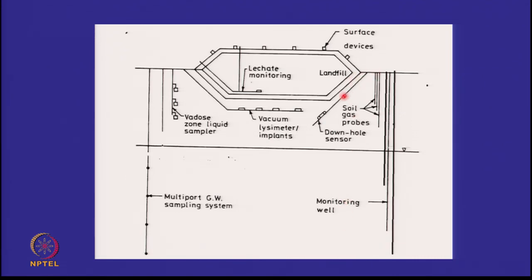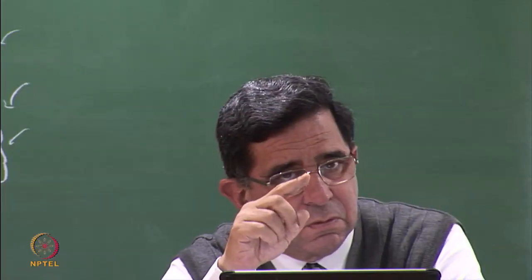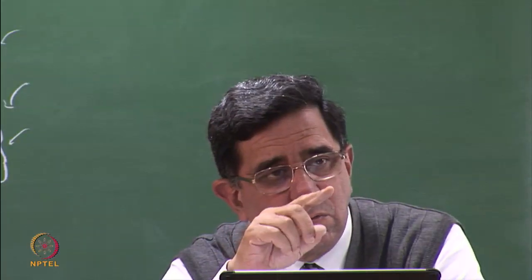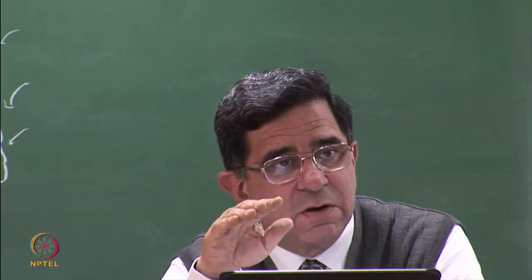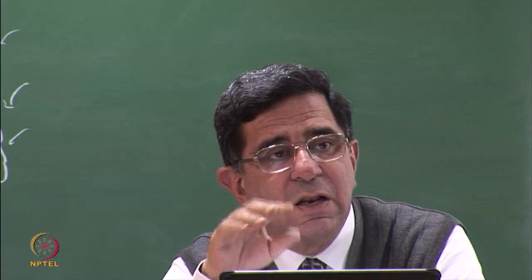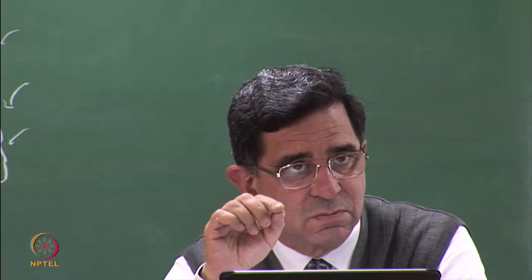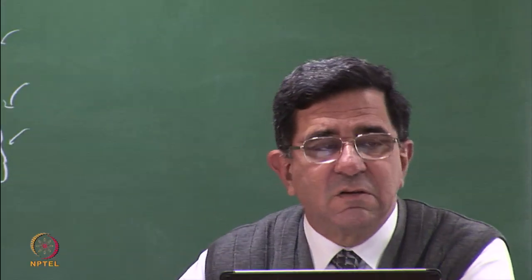So, this looks very nice, but I can still miss a leakage which goes from here. Which brings us back to the basic concept that I want to monitor everywhere. How do I monitor everywhere beneath a landfill? By putting a leakage detection system. So all this is rarely done.